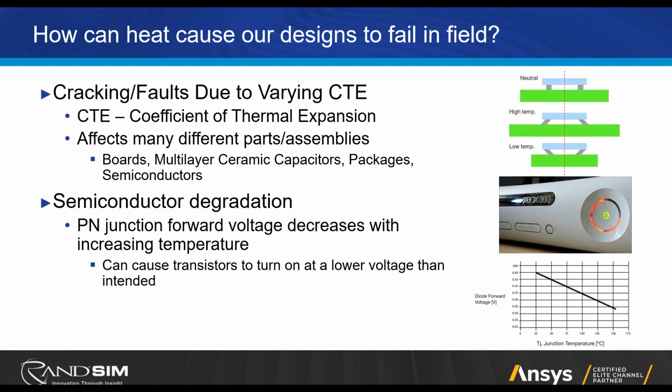This is a really big one, and it's kind of broad and it affects many different types of things. So the first thing that might come to mind is your solder joint fatigue here. That's illustrated on the right. What you have in this little diagram is 3 different temperatures and then kind of an illustration of the mechanical stress and strain that's going on.